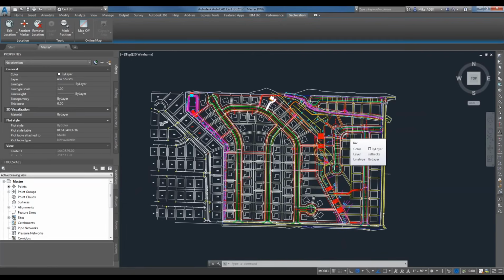However, in Civil 3D, we use COGO points, short for coordinate geometry points. They're a little bit different from those normal AutoCAD points. You could have plenty of properties associated with them. So you could have point numbers, point names, descriptions. So if you are surveying out in the field, you can bring in points with descriptions. You can tell them apart. So you can do top of curb, bottom of curb, center line of the road, etc. So COGO points do allow you to have a little bit more customization. And they also let you have them outside the file, whereas in AutoCAD, they're inside your AutoCAD file.